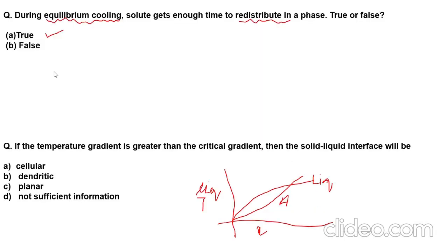There is a case where you have been discussed about how this interface will be transferred with respect to your solidification. So if initially a certain solid is created like this, you have a solid liquid interface, then after a change in your temperature, your interface moves like this, right? Your solute concentration from the liquid will decrease and your solid interface will try to increase into the liquid. There is a movement of this interface from left to right.